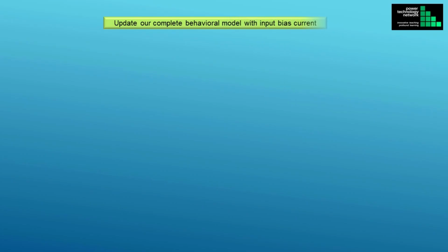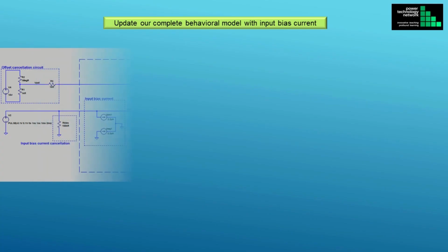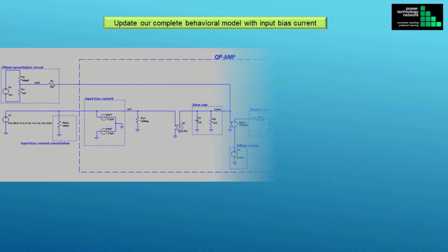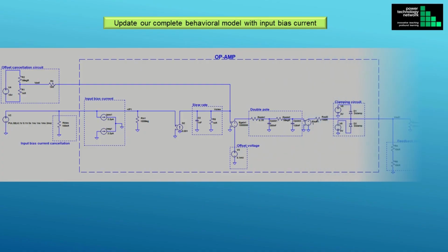So far, we explored several op-amp characteristics. We added internal poles to limit the bandwidth, we added clipping, slew rate, input offset and input bias current, to the ideal op-amp circuit model. We have built out the ideal op-amp, to include various imperfections. The internal circuitry is shown within the large rectangular box with the dashed line type. There is some external circuitry, outside the box, that we added to counter the effect of some of the imperfections, which we shall identify. Starting from the left, the imperfections are: input bias current.